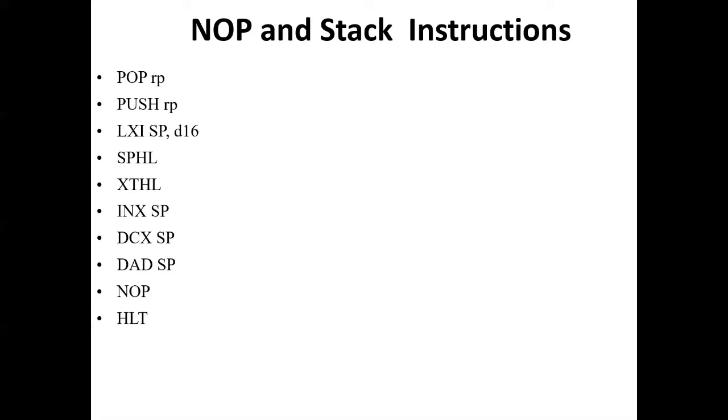Next is NOP. NOP is an instruction that cannot be classified under any group of the instructions. NOP is a mnemonic that stands for no operation. This instruction does not do anything. Still, it is quite useful. It occupies only 1 byte in memory. It has the opcode 00H.